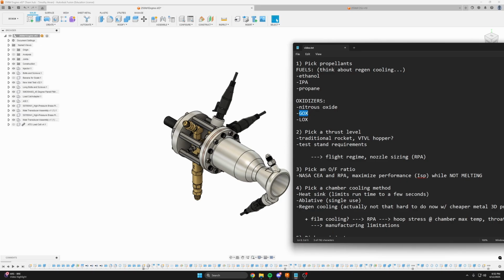You have to clean everything very well, to oxygen service level. All your lines and all your fittings need to be free of debris that would get accelerated very fast and could potentially trigger something bad, some kind of energetic event.